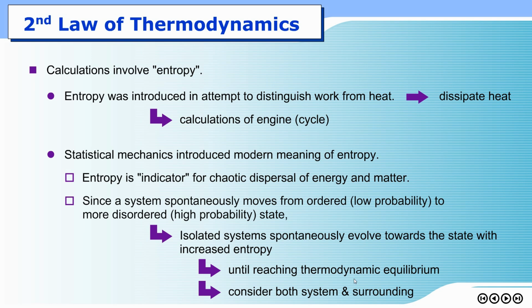We just consider change through system boundaries and then reflect that to be the change in internal energy of whatever is inside the system. We never consider internal energy of the surrounding in the first law. But for the second law, in order to predict the change, whether it is spontaneous or not, we have to consider the change in entropy for both system and surrounding.